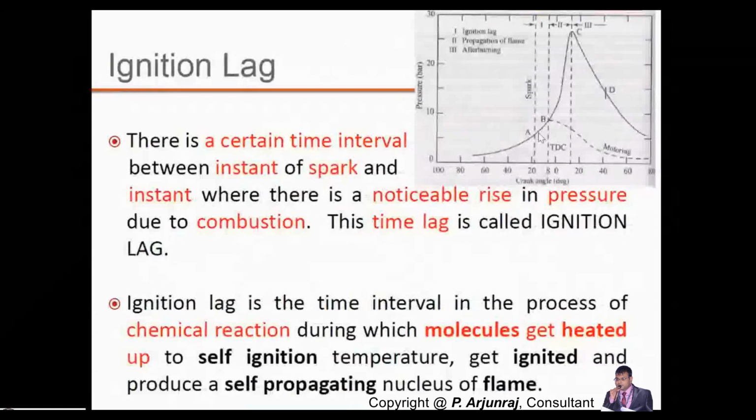So the first stage is nothing but the ignition lag stage, A to B. There are some facts you need to understand about the ignition lag. It is always a time interval between the instant of spark and the instant where there is a noticeable rise in the pressure due to combustion. So you will not get the combustion immediately. That's what I also told you. You need to have some time.